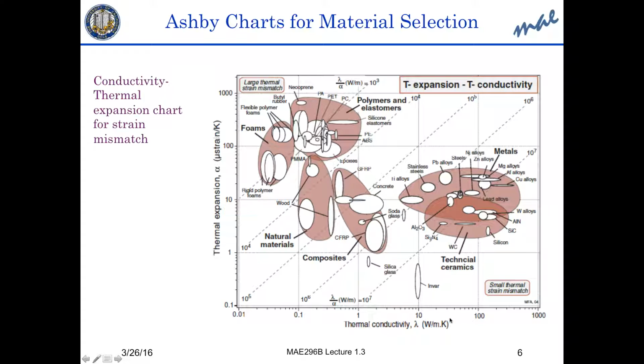So the thermal conductivity is on the horizontal, the thermal expansion on the vertical. So you will see now, if we look at all the metals here, very interesting, the microstrain is between 10 to 20 to 30 in this range. So they are limited in their expansion. If you look at ceramics, it's well below 10. So you have, for example, tungsten carbide is a few, 3 or 4, glasses and so forth are kind of low. So these will have lower strains, and these will be a little bit higher strains.